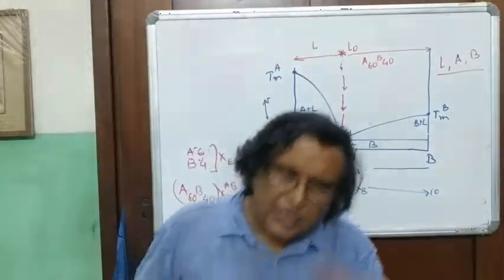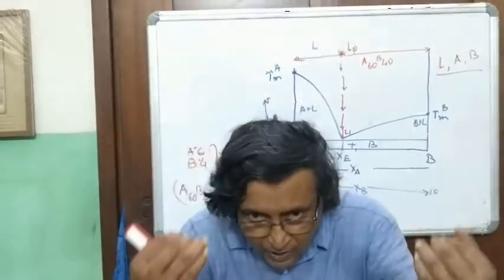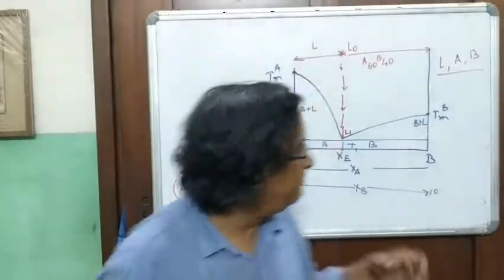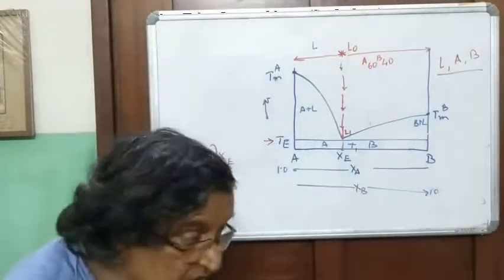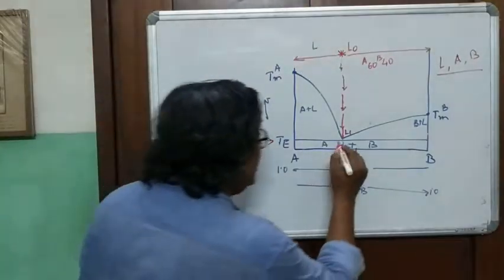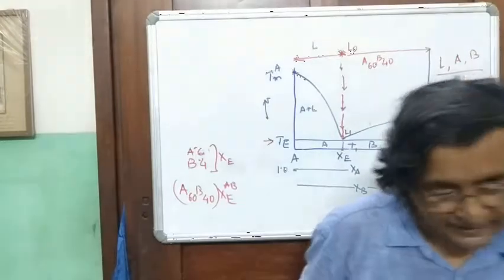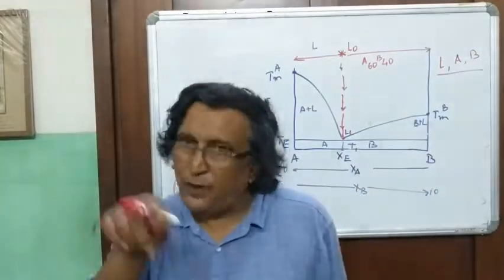But the proportion of the melt will decrease and more A and B precipitate out in the same proportion as in the eutectic. And this I can't show. So this is a situation where your liquid composition and solid composition coincide. The liquid composition and the solid composition coincide.